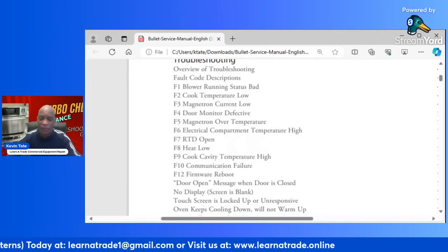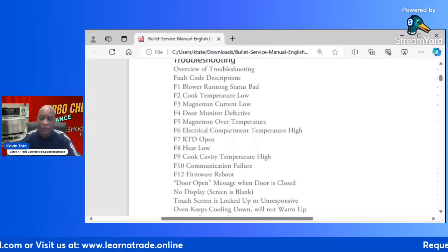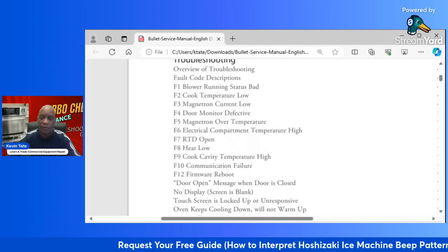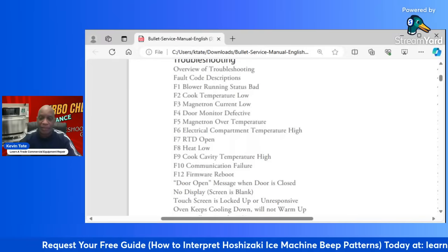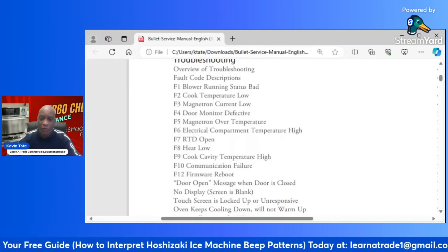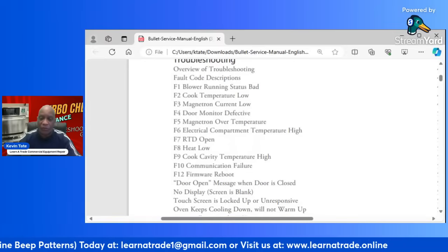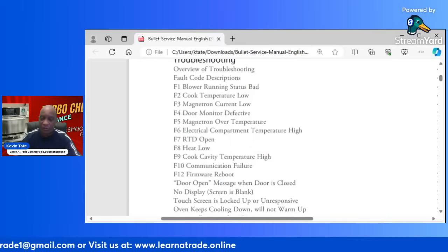If both of those are checking out okay, then you may have an issue either with your lower heater or your upper heater. And in that case, you have to ohm out each of your heaters, and then that'll let you know. Because if your heaters are bad, it's just going to give you open line on your meter anyway.